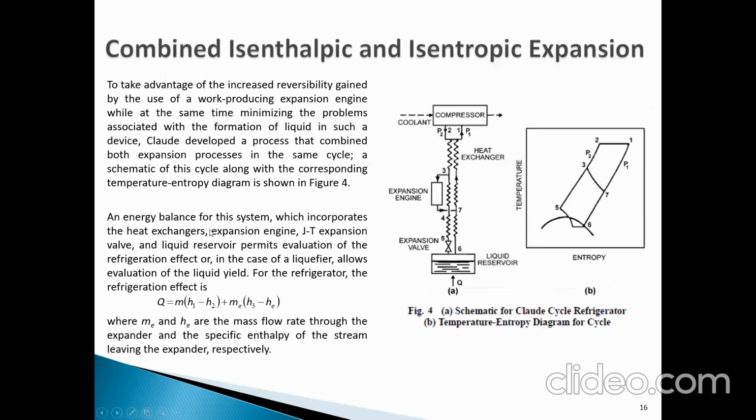Combined isentropic and isenthalpic expansion. To take advantage of the increased reversibility gained by the use of a work-producing expansion engine, while at the same time minimizing the problems associated with the formation of liquid in such a device, Claude developed a process that combined both expansion processes in the same cycle. A schematic of this cycle along with the corresponding temperature entropy diagram is shown in figure 4.